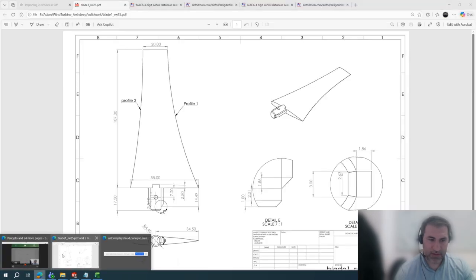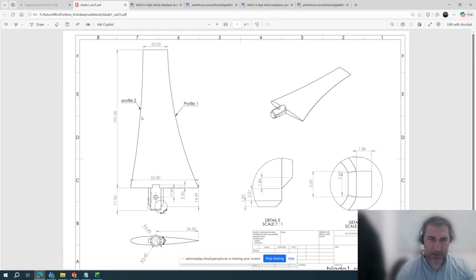And as I said, in the middle, I'm going to have another airfoil. Perhaps you might have 10 airfoils, so you should have 10 chord sizes, and perhaps the airfoils are even different. So you have to download different airfoils from the website and change their chord size accordingly. For the sake of demonstration, I'm going to have another airfoil here in the middle.